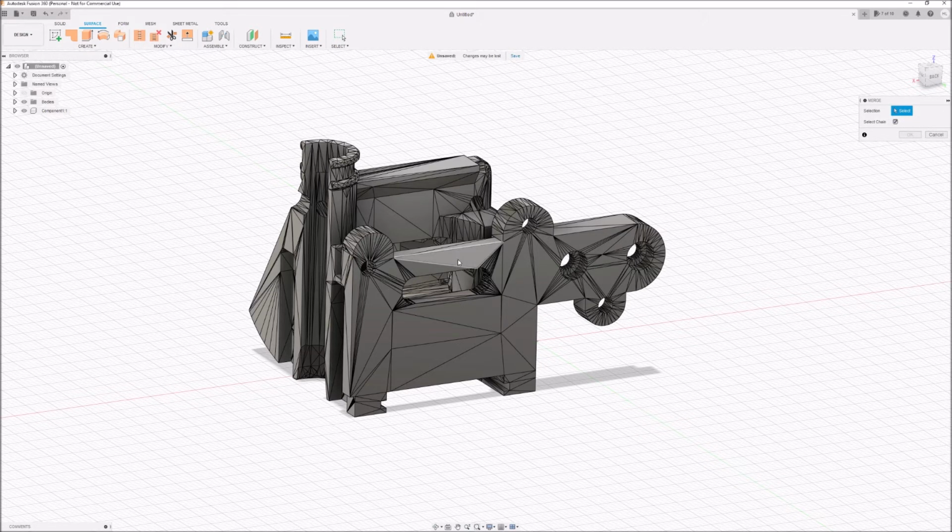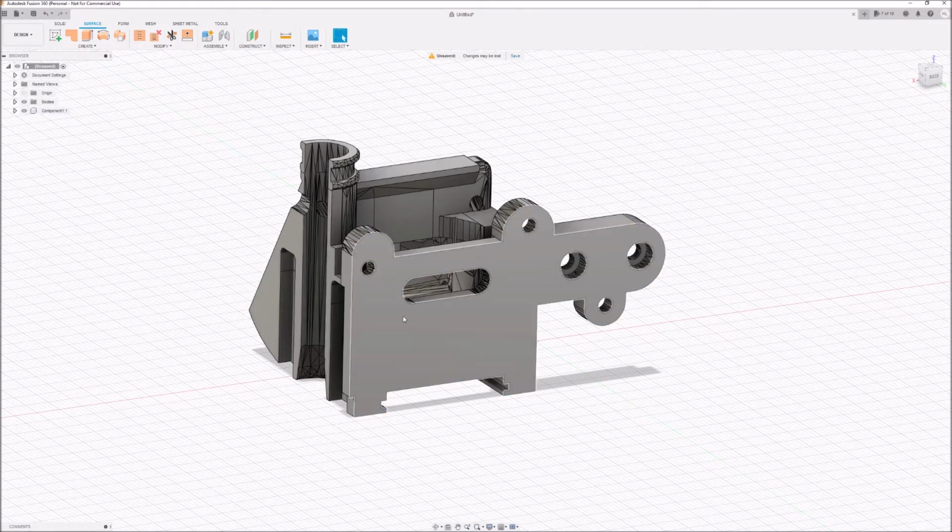I'm going to click on one of these faces, and these actually all make up this surface, this side of it. But something happens when it gets converted to an STL file to create these, something beyond my knowledge. But we want to clean this up so it's easier to edit. So I'm going to click OK. It's going to merge these into a single editable surface.